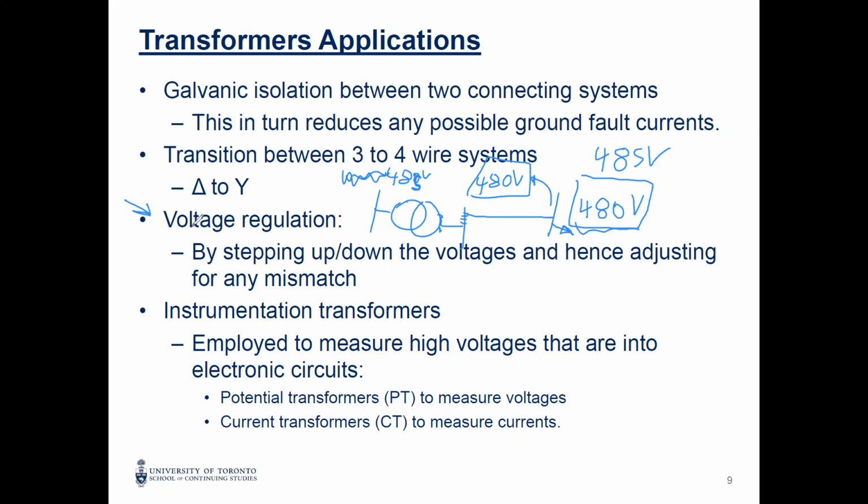And we call this kind of transformers, and we have them here in Ontario, the voltage regulation transformers. So they are not changing the voltage much, they slightly change the voltage, and they have something called the taps. We will discuss it later. So the taps or the tapping of the transformer, we can change to make this voltage constant, even with the changes here in the transmission system.